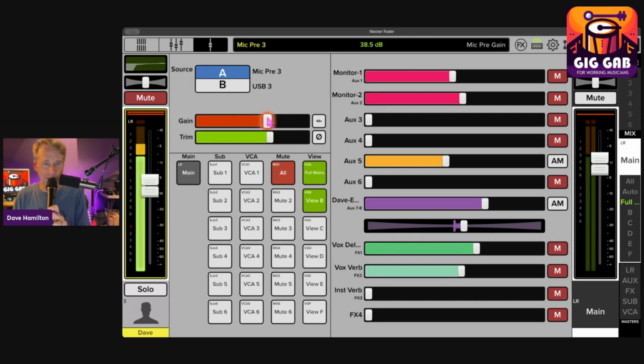And I just start moving the gain up and down until, first of all, I get it to stop peaking and have enough signal, because you're going to be amplifying this. Whatever it is you have in there, you're going to be amplifying. And so you want more signal than not, because the part that is not signal is, at least potentially, noise.